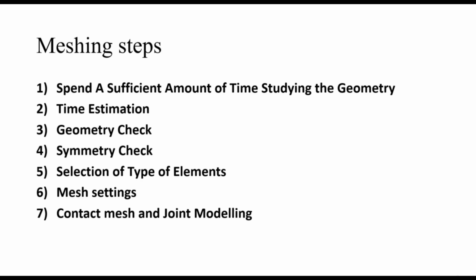Then, coming to the third step, we need to check the geometry. Once we import the geometry from other CAD systems, we need to check whether any losses were created during the transfer process, or whether any data loss has occurred. Then the fourth one is the symmetry check.